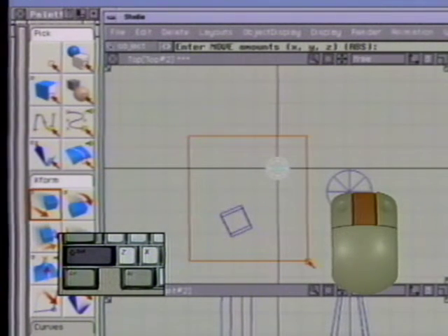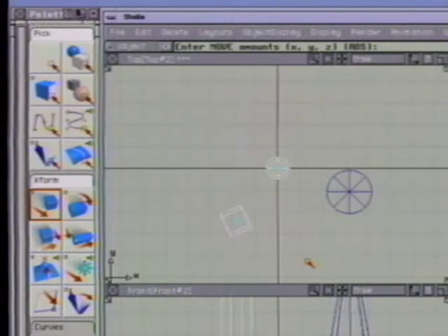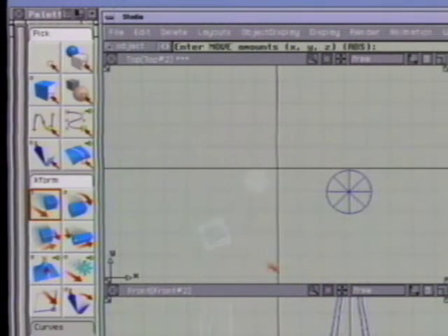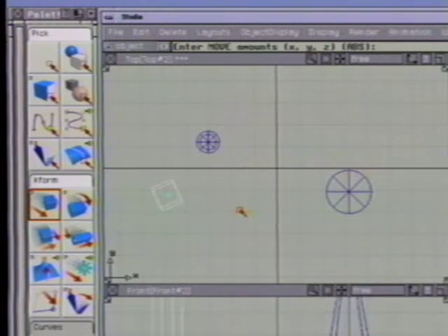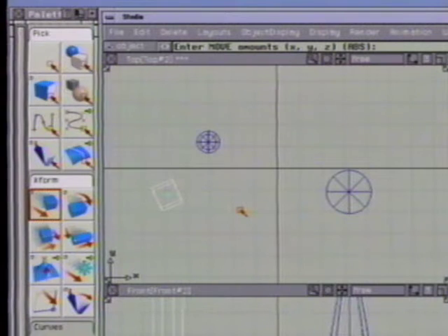Now, press the Shift key and click drag a pick box with the middle mouse button around the cube and the cone. Click drag to move the new selection. The middle mouse button allows you to replace the existing pick selection with the new selection. Similarly, the Shift key and the right mouse button can be used to remove an object from the selection set. By using the Shift key, you can use the mouse buttons to create selection sets without leaving your current Xform tool.